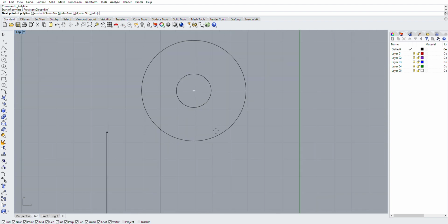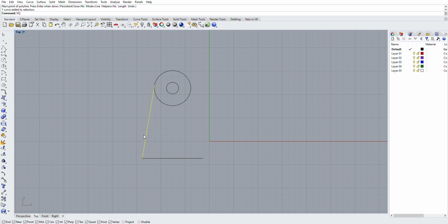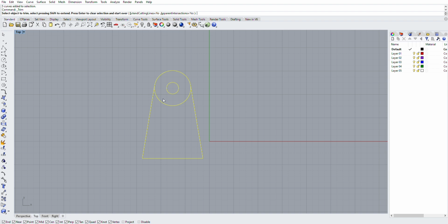From there, we can click a line from the end of the line, and we don't want the center that it snaps to, we don't want the end, we want it on tangent. Select our line there, use the mirror command, mirror off the center of our line, which came from the center of our circle. We can now select everything, grab the trim tool, and cut the center out, and just that quick. We have a shock tab now.